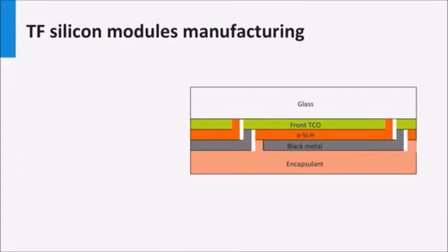The configuration of solar modules of thin film PV technologies is different from those based on crystalline silicon-based wafers. Here we will show the concept of how the solar cells in a thin film PV technology are processed and interconnected. We will show it here for a thin film silicon PV technology. In the next blocks, we will discuss other thin film technologies like CIGS and cadmium telluride. Similar interconnection schemes are being used for these technologies.